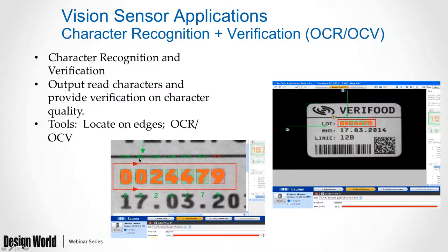But the verification part comes in where I can set tolerances based on good characters, to see if I have a bad character that's been put on. So if I've got an inkjet printer putting on a date lot code, you'll see here R9 is at about an 85% match of what the initial pattern was. Now we can set that tolerance, and we might want to kick out anything below 90%, or depending on what it is, start to fine tune that over time. So we're actually doing character reading, but also verifying that you have, say, a correct date lot code as it goes out the door.